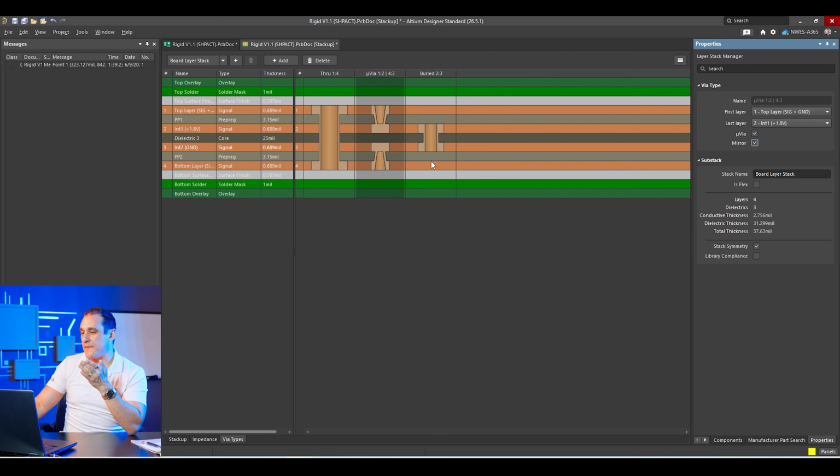Now with this type of via definition in this design, you could actually route from layer 1 to layer 3, or from layer 4 to layer 2, or any of these other combinations that we see in the PCB layout, and it will actually be manufacturable. Now the only difference here is in the manufacturing process. Here these outer layers are going to be manufactured with laser drilling.